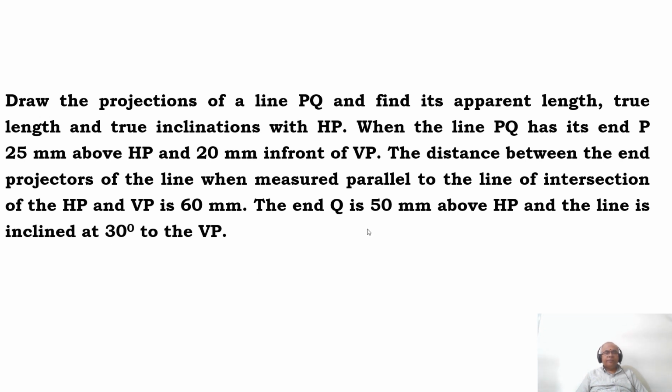Now, in this video, we will take up one more problem on projections of lines: how to analyze this problem in 3 dimensions and also how to solve it by using the manual sketch. The problem reads as: draw the projections of a line PQ and find its apparent length, true length and true inclination with HP.